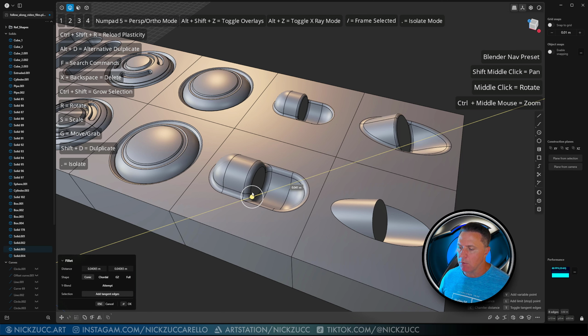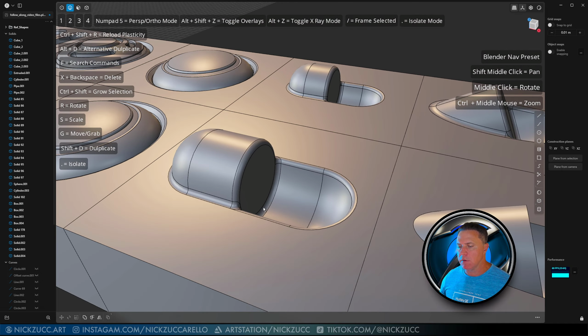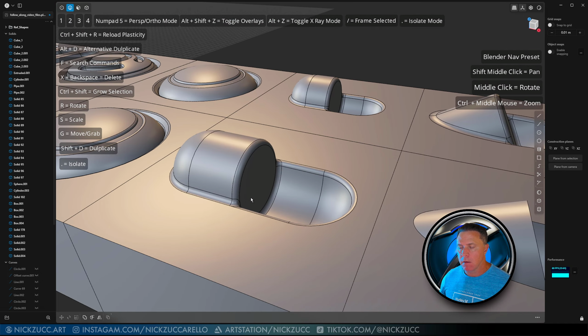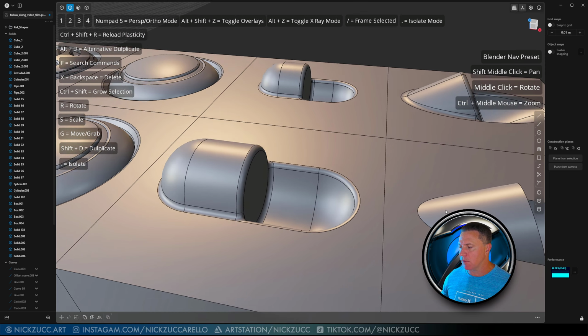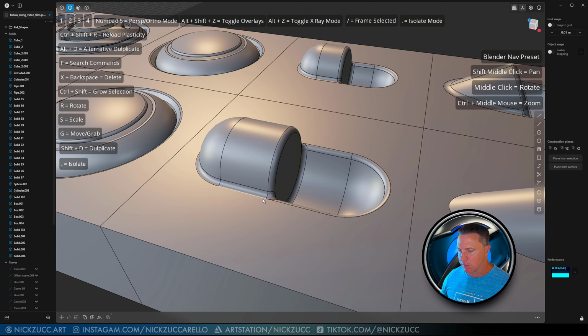Okay, so I'm going to go ahead and just leave this as is for the fillet. I do like the look of it. I'll probably just drop it down to something like 0.02 and 0.02 for that. Hit OK, and we're good to go. Now, if you wanted to do a chamfer on here, this is going to be very similar to what I'm going to have to end up showing you on this. This is going to probably be a lot of work over here for this one.